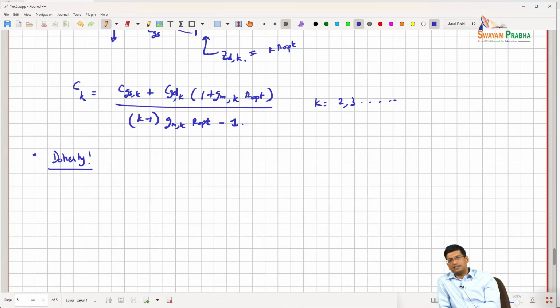So typical designs have been at 4 stack or 3 stack. Yeah, between 2 and 4 is generally the number that in practice people have been stacking. The breakdown voltage limit, you can maybe go 5 VDD also works. I think there was a paper at ISSCC several years ago which had 6 stacks, but that was a line driver, not a PA, but the same principle basically.